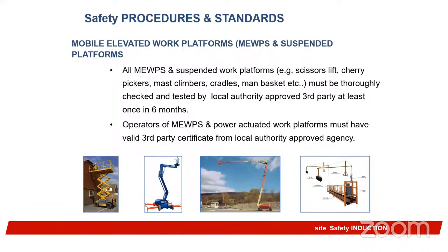Mobile elevated work platform, MEWP, you should also talk about it if it's what you use on your site. For all mobile elevated work platforms, you have scissor lifts, cherry pickers, mast climbers, cradles, man baskets. No matter what it is that you use, it must be thoroughly checked and tested by the local authority. We will call it simply a third party certificate. You should have third party certification for all your heavy duty equipment or all your elevated work platform equipment.